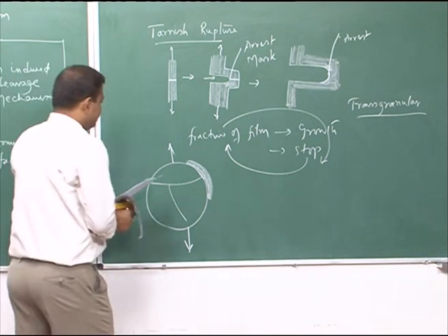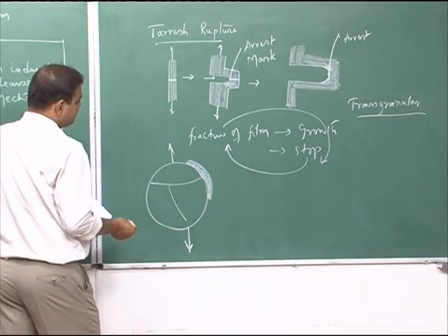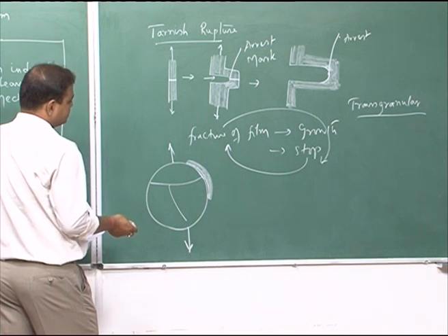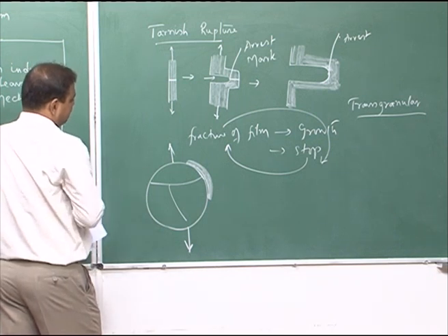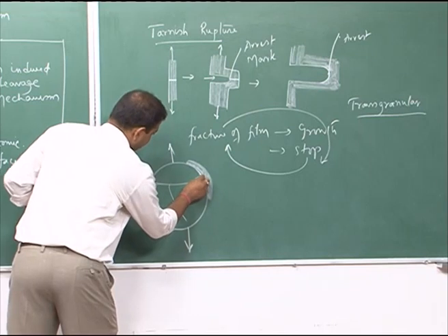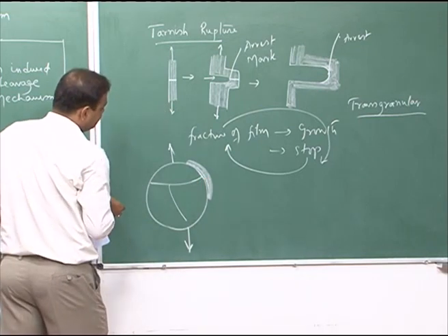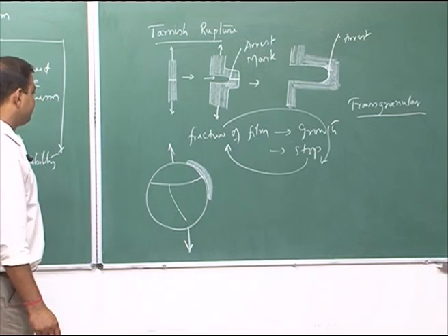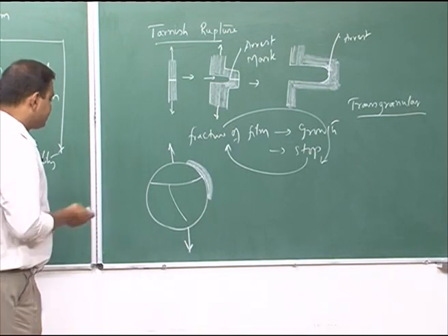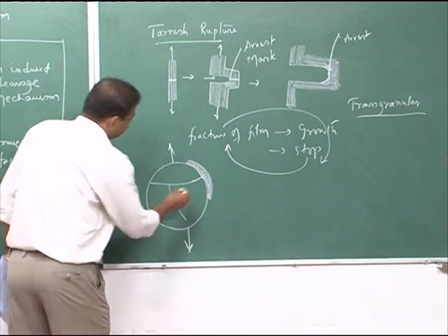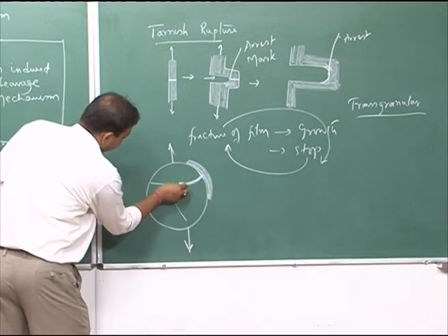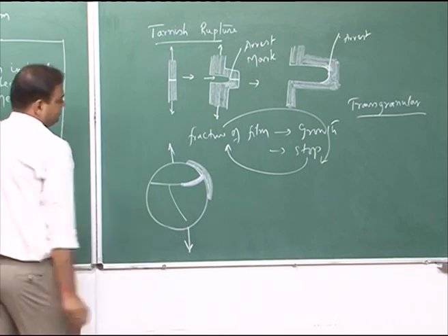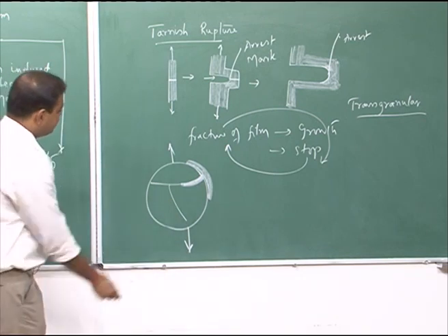Now, at this grain boundary, the tarnishing action, or the oxidation or film formation, because the grain boundary zone is a highly diffusive zone because of selective precipitation or selective segregation along the grain boundary, this zone will get tarnishing. Tarnishing would happen in this zone.